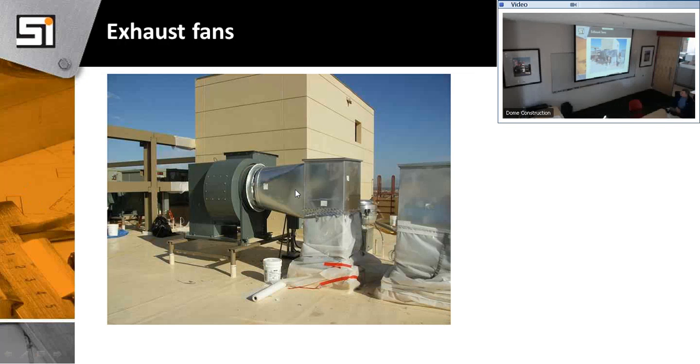Exhaust fan, centrifugal exhaust fan, no stack, they're in mid construction. Actually not a good inlet condition, so this fan, as an engineer, I have to derate the performance of this. But you know what, roofs get so tight, I never get to do everything I want.